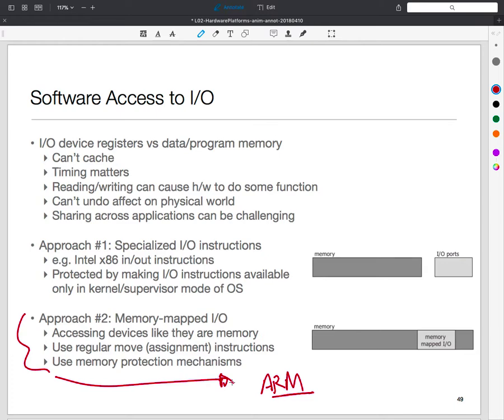Now, our particular processor doesn't even have cache, so you don't have to worry about it. Remember, these are MCUs. All the memory is sitting on chip. So usually you have caches only when you have to go on and off chip. If memory is on chip, then it's already pretty close to the processor. There is no need to have a cache. So we don't even face that issue out there, the caching issue.